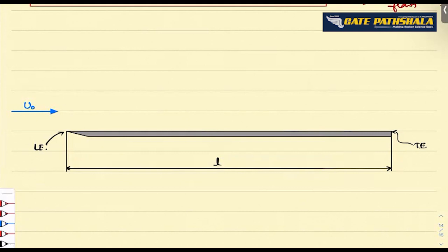Yes, sir. Okay. Now, when the fluid comes in contact with the solid surface of the plate, the adhesive nature of the fluid, because of its viscosity, makes it start to shear on the surface of the plate, and as we go perpendicular to the surface of the plate, the velocity will increase. On the surface of the plate, the velocity with respect to this stationary flat plate becomes zero.